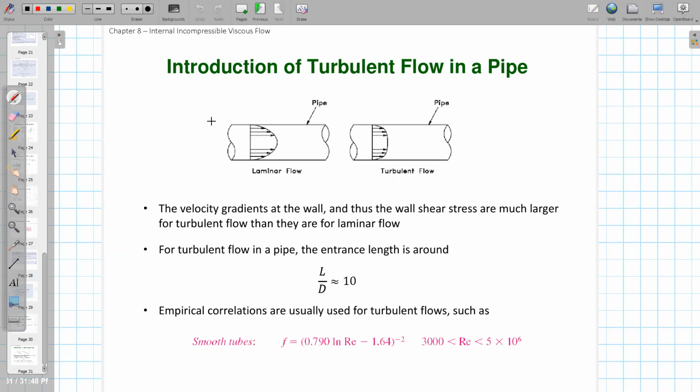On those experimental data, we see what things look like for the turbulent flow. One thing I also want you to know is that the velocity profile in the turbulent flow is different from the velocity profile in the laminar flow. This picture shows what it looks like. For the laminar flow, this is the velocity profile. For the fully developed turbulent flow, this profile becomes something like this. You will see that the maximum velocity is reduced. This slope is very steep, but the slope here is not that steep. Instead, you have a very steep slope close to the wall.